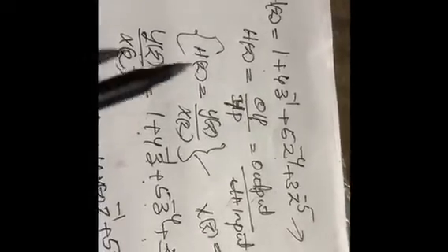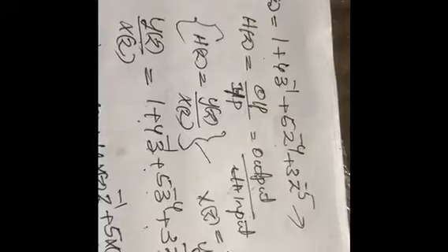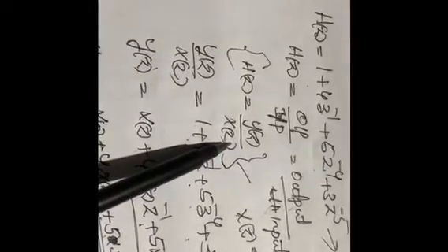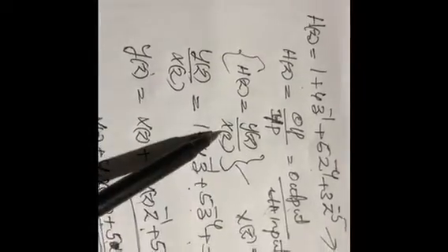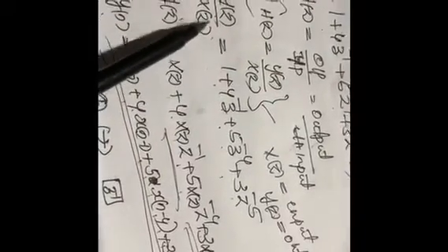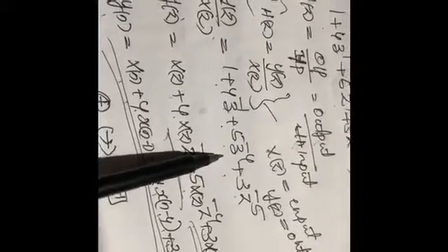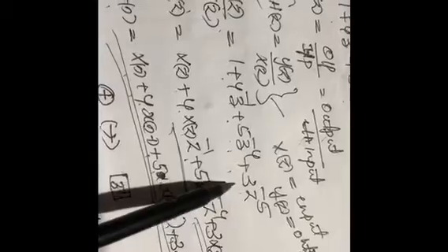Let us take X(z) as the input and Y(z) as the output. Now, the system function H(z) becomes Y(z) by X(z), that is output by input. Let us replace the above equation number 1 by this equation. We got Y(z) divided by X(z) is equal to 1 + 4z^-1 + 5z^-4 + 3z^-5.